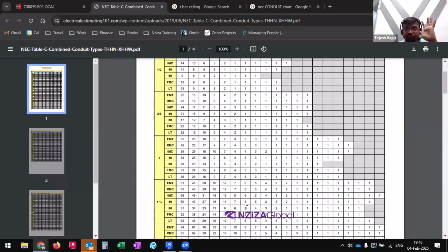5. A total of 5 number 3 conductors. Now, if it can handle 5, it can properly accommodate 5. It will accommodate even 4. Essentially saying the conduit size might be a bit big for the given 4 conductors that we are talking about. But that is fine. As long as we are not undersized, it is fine. You can go to the next possible option over here.